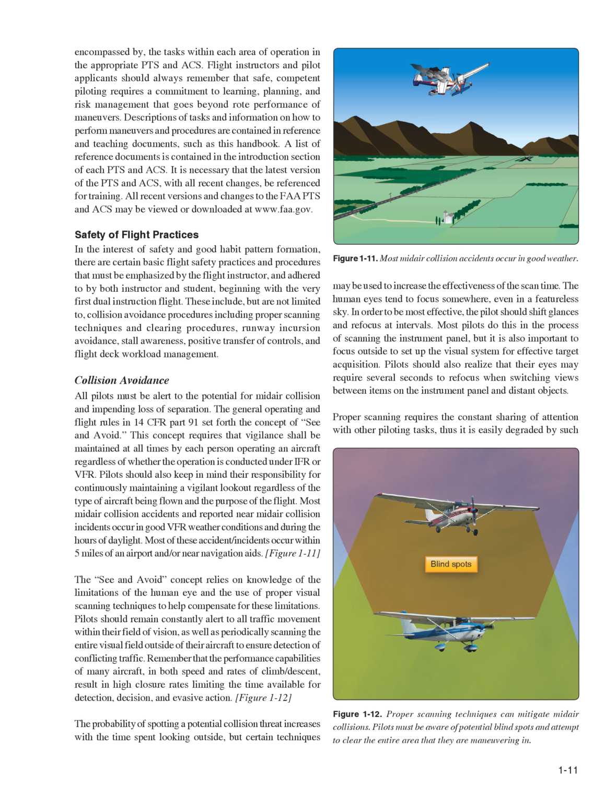Safety of flight practices. In the interest of safety and good habit pattern formation, there are certain basic flight safety practices and procedures that must be emphasized by the flight instructor, and adhered to by both instructor and student, beginning with the very first dual instruction flight. These include, but are not limited to, collision avoidance procedures including proper scanning techniques and clearing procedures, runway incursion avoidance, stall awareness, positive transfer of controls, and flight deck workload management.